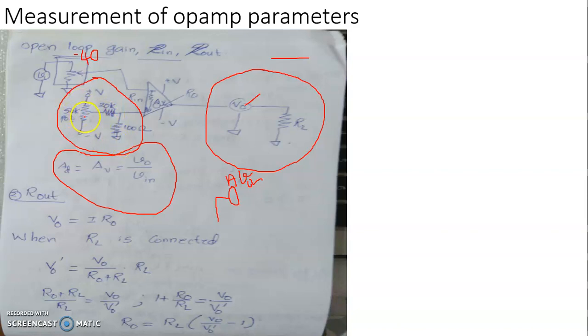That happens to be the input voltage which we have connected, because this terminal is at AC ground. Here you apply a DC compensation and the input AC is given to this terminal. So the differential input AC is Vin minus 0, that is equal to Vin. So the output will be equal to A times Vin taken across an extremely small resistance referred to as the output resistance or output impedance of the op-amp. Ideally, this has a value 0. Practically, this is of the order of a few tens of ohms.